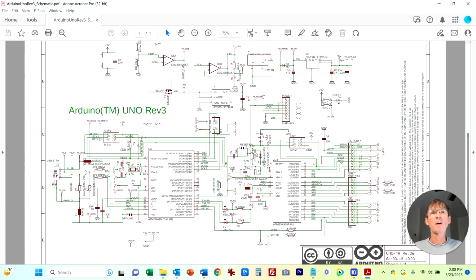So it would be impossible to program this through a USB interface without having a special converter that converts between USB to what's called UART. And UART is basically a simple serial protocol that any microcontroller supports. USB is quite a bit different. So this basically just takes the USB, converts it to a UART or just a serial protocol, and then that gets passed on to the primary microcontroller.